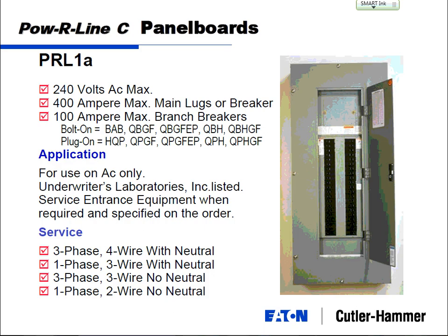Okay, so this is the snapshot of that panel board. As I mentioned, 100 amp max branch breakers, 400 amp max main lugs or a main breaker, and 240 volts. So that's single phase or 208 three-phase.